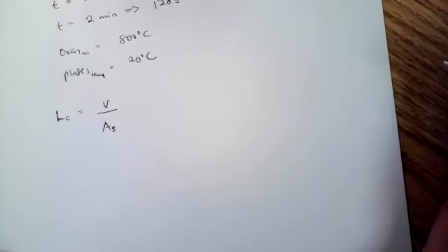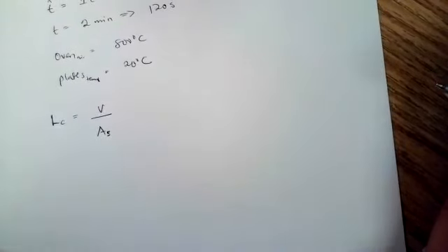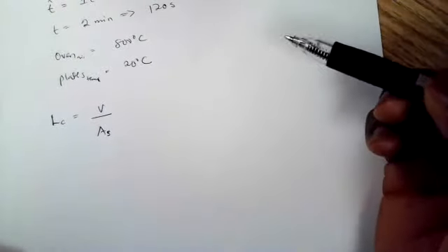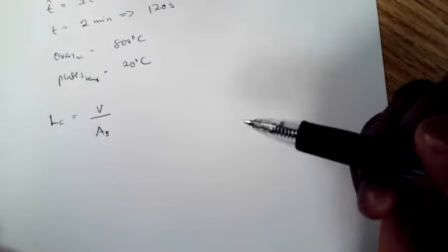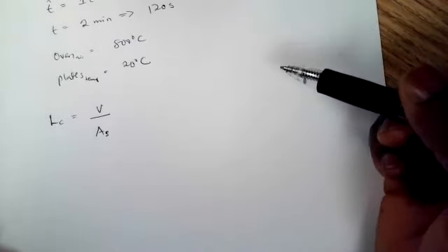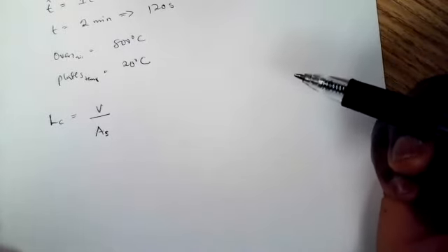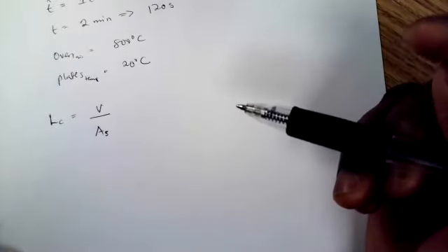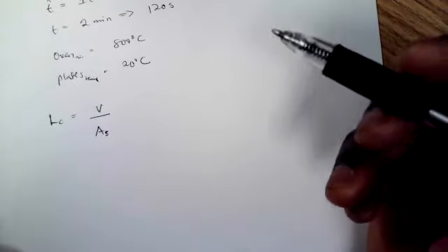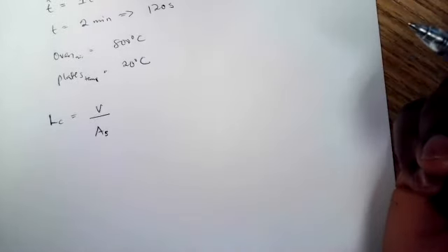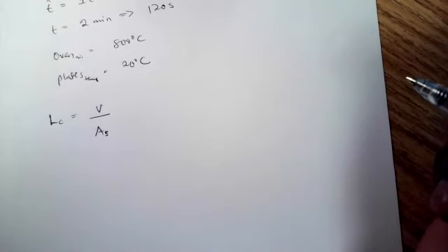Well, I'm looking at this and I just can't seem to find the connection between the solution we have here and the question. Because if you're looking at the characteristic length of the brick wall in the oven, then surely you have to consider that the Biot number depends on the dimensions of the oven, and that has not been given in the question.